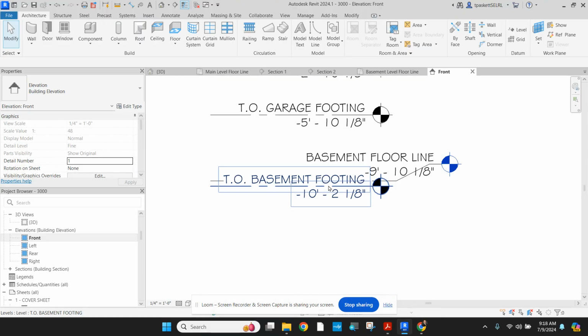We want to make sure our footings are below that so that when that frost or freeze happens, it doesn't expand the moisture to the point where it raises the buildings up. That's kind of an important thing to do. It's called frost heave, and when ice freezes, it expands, and we don't want to raise the buildings because then when it thaws, it's going to drop the buildings, and they are not designed to handle that kind of abuse. So we want to make sure that our footings are below the frost depth, and that is the entire footing needs to be down below that.